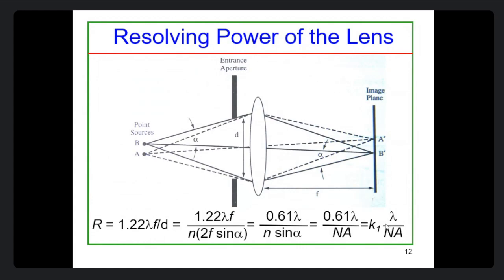So from here, what we can understand is that to get very finer or smaller image or dimension or image lines, whatever you say, on this image plane or the wafer, you have to go for higher N, meaning numerical aperture should be high. Now what is numerical aperture?